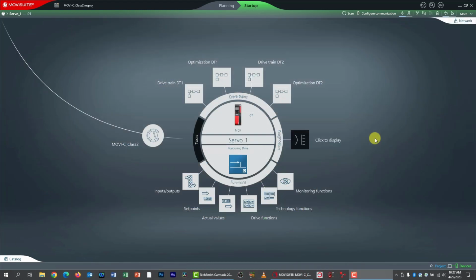We're going to finish up this lab by playing with a few referencing modes. So far, we've kind of used the cheating referencing mode where you just say, wherever you are, be referenced. That's easy, that's fun, but it's not necessarily realistic. We need to play with some of the ones that actually move the drive and use referencing sensors like referencing cams and the limit switches.